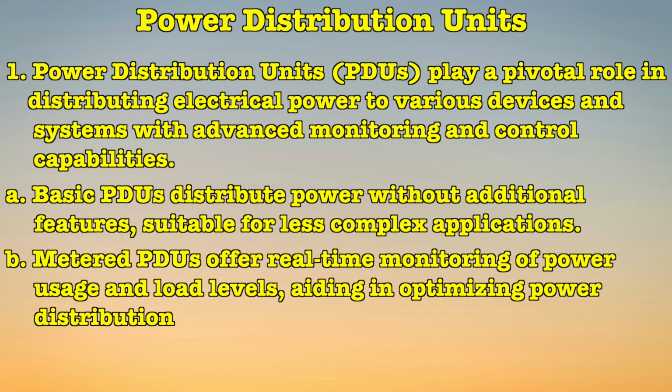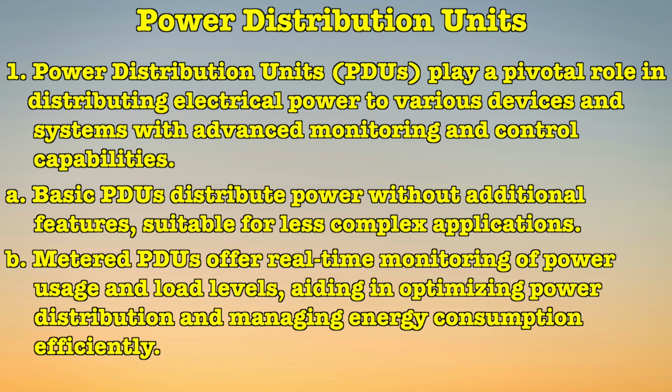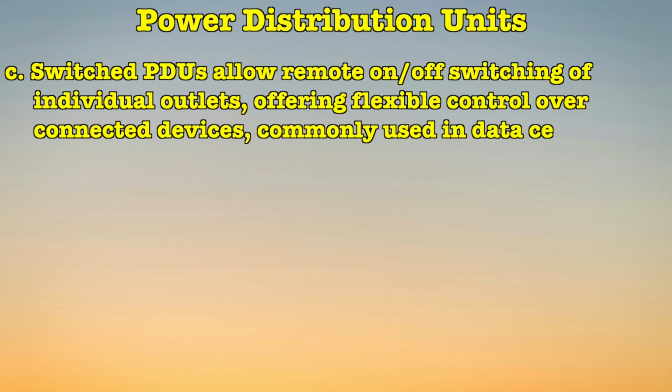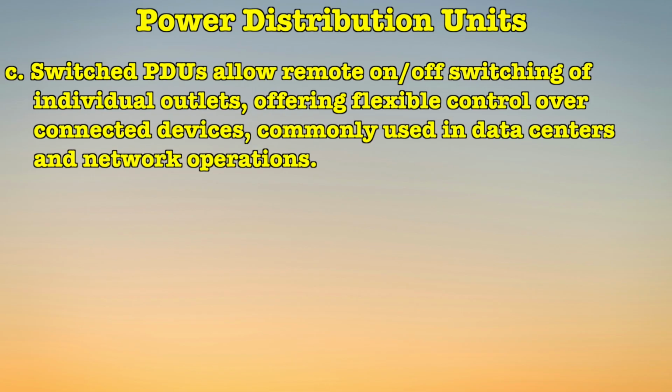Next one is metered PDUs, which offer real-time monitoring of power usage and load levels, aiding in optimizing power distribution and managing energy consumption efficiently. Next one is switched PDUs, which allow remote on-off switching of individual outlets, offering flexible control over connected devices, commonly used in data centers and network operations.